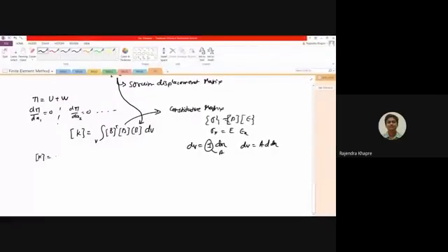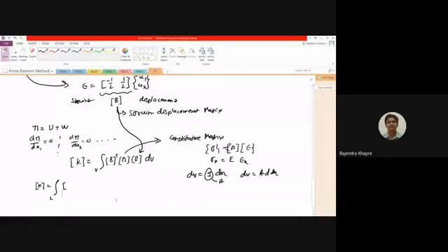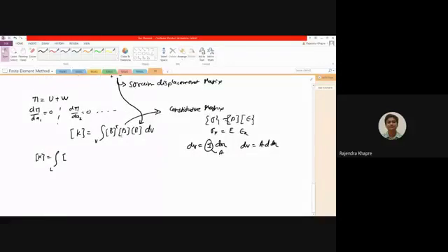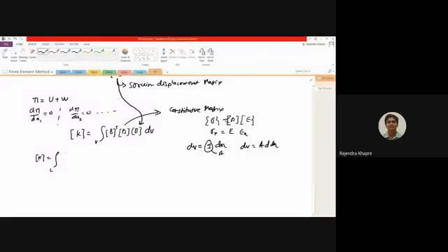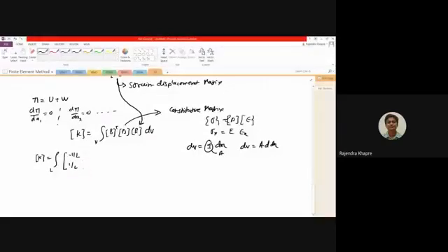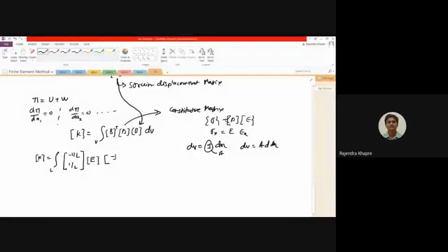So this is the stiffness matrix. Now I am writing integration over the length. Your B transpose: just now we have calculated the B value. B value is minus 1 upon L and 1 upon L. If you rewrite the expression in terms of its transpose, it will be minus 1 upon L, 1 upon L. So this is B transpose. Your D value is simple E, your B value is minus 1 upon L, 1 upon L, and then dV can be written as A into dx.